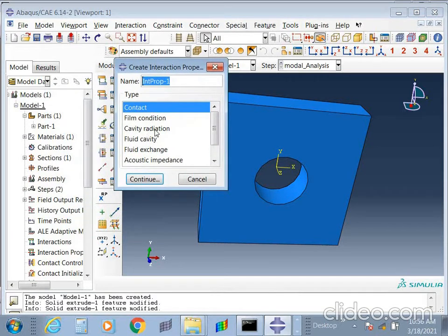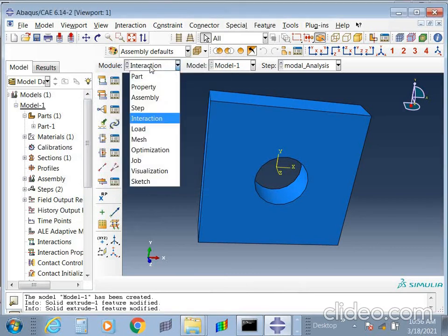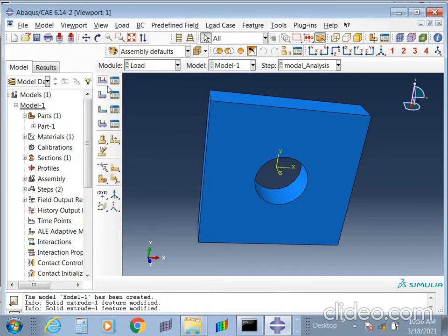Yes. So moving further, load. Now for modal analysis, to calculate a natural frequency, we don't require an external load, because it's a property of the body. For an initial excitation, it will oscillate a number of times. So we don't require load. All we require is a boundary condition.